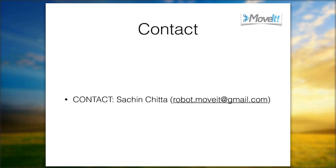There's a question about whether there is some extended documentation about the planners in MoveIt and OMPL. Mark, do you want to take that one? Well, there's the OMPL website, but that doesn't talk much about the integration with ROS. So I think the MoveIt website is probably the best resource for finding out how OMPL is integrated with the rest of MoveIt. If you're looking for information on how MoveIt talks to OMPL and how MoveIt uses planners, you should go to the MoveIt website itself. If you're looking at the OMPL planners themselves, then look at the OMPL website.